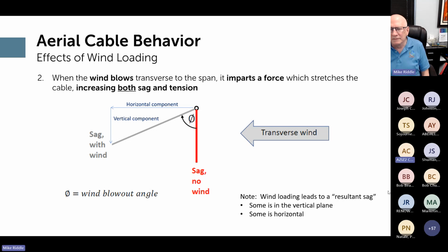Yes. I understand this conductor blowout, which you named horizontal sag, and the impact of wind and ice. Once we calculate sag, we use resultant weight because of conductor wind pressure and ice loading. I am familiar with that process, but the term horizontal sag I probably heard for the first time. So it's good information. We call it conductor blowout.